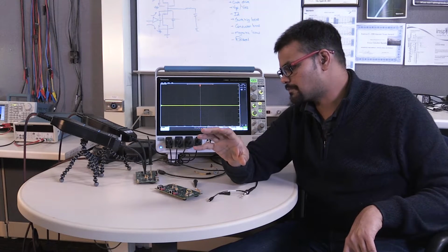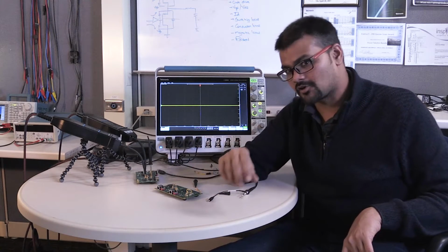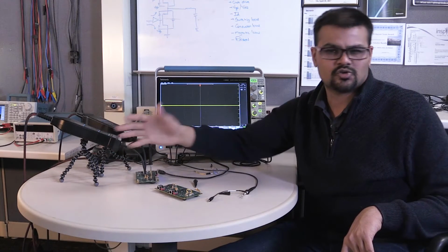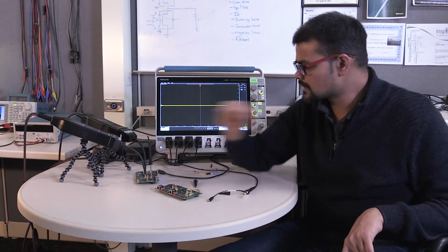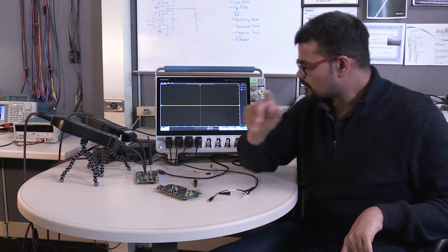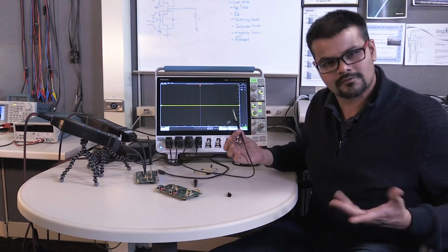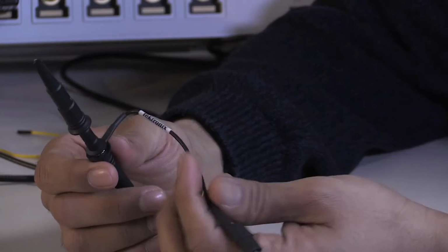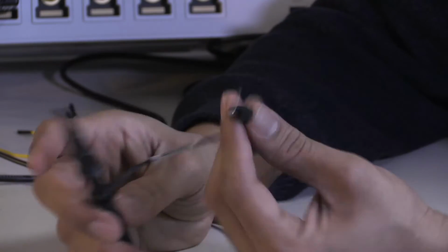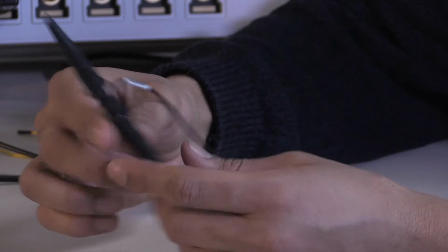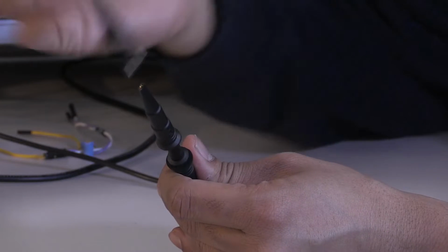So if you're trying to measure gate measurements or shunt measurements, TIVM is the product for you, and then for higher voltages you usually use a TIVH. So those are the probes, and last but not the least, we'll use the TPP1000. These are the passive probes. We all know this is a standard probe, and one of the challenges is obviously the ground loop. As soon as you have this ground loop, there's not much you can do with this measurement. So this has to go. This is a no-go. It cannot work.